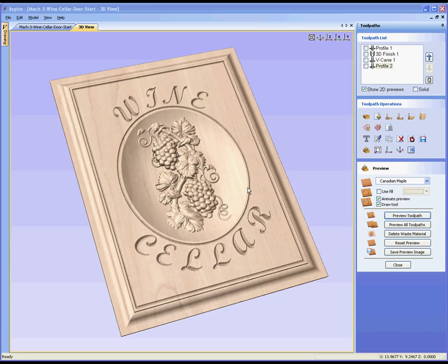In order to set that up, we needed to define the geometry for the tool, add it to the tool database as a form tool, and we needed to offset the vector by the cutting distance that we wanted that to come in around the edge. After that, it was fairly straightforward for us to generate that profile toolpath, and the only additional option we needed to check was to make sure that it was set to do sharp corners so that the tool didn't roll around those, and it gave us the effect that we can see on the screen.